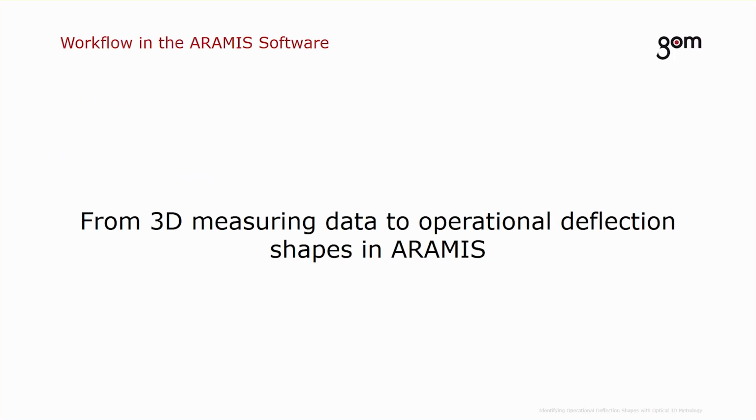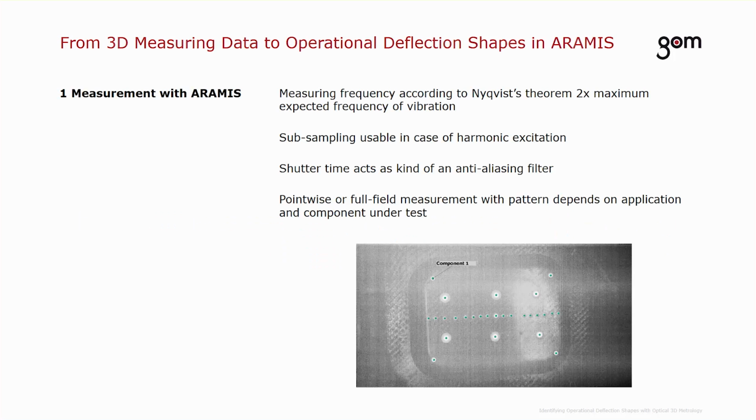Now let's have a look at the actual workflow that is behind the results that you have seen in the application example. So I want to show you how you get from 3D measuring data to operational deflection shapes in Aramis. To start with, of course, we have to do our measurements with the sensor to capture the images. We will choose our measuring frequency according to the Nyquist theorem to be 2 times the maximum expected frequency